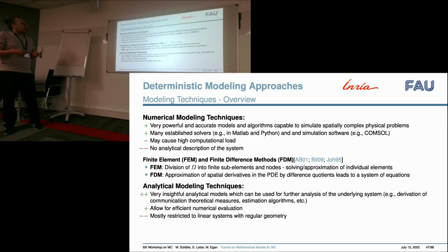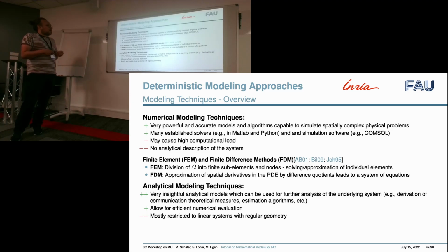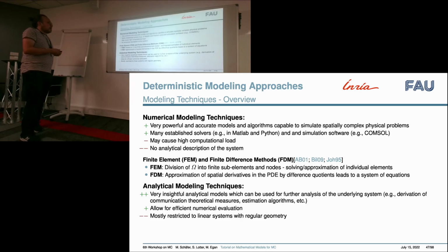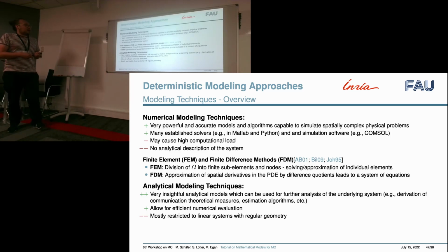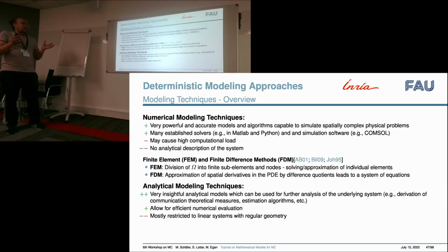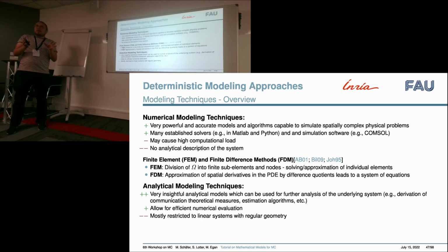But on the negative side, they may cause high computational load, and I think the most obvious drawback is that we have no analytical description. We run a numerical simulation, we get a set of numbers, and then we run it for a different parameter set, we get another set of numbers, but it's hard to relate parameters to the output. I think the two most prominent examples for numerical methods are finite element methods, which divide the spatial volume into sub-elements and then you solve these individual sub-elements.